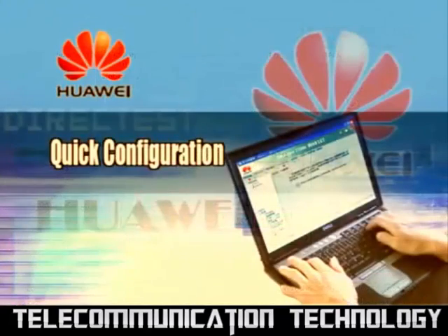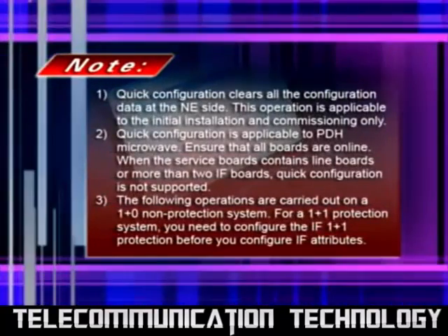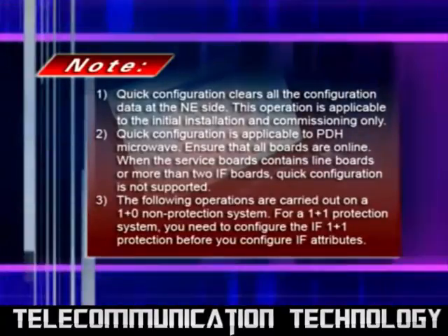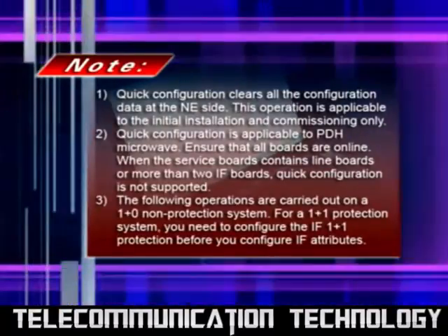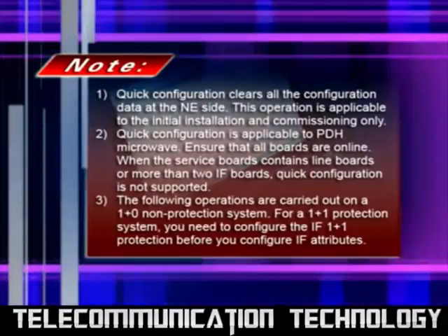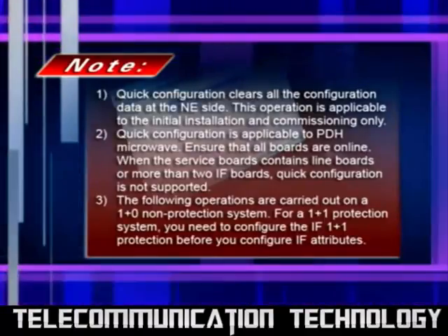3. Quick configuration. Note: 1. Quick configuration clears all the configuration data at the NE side. This operation is applicable to the initial installation and commissioning only. 2. Quick configuration is applicable to PDH microwave. Ensure that all boards are online.